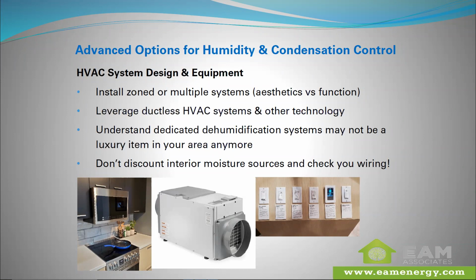For most air conditioning systems, dehumidification is an uncontrolled byproduct. In most cases, people are not using the more advanced systems and thermostats that close on humidity. That thermostat is only closing on temperature. Depending on what the indoor and outdoor conditions are, and you have a coastal area down by you, just like we do, it's not always that hot, humid day that's a problem. Sometimes we have high outdoor moisture loads during cooler outdoor temperatures because of that proximity to the water. So you just may need that dehumidification system at some point.